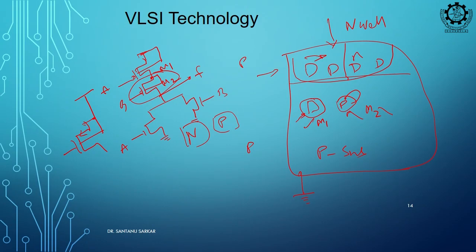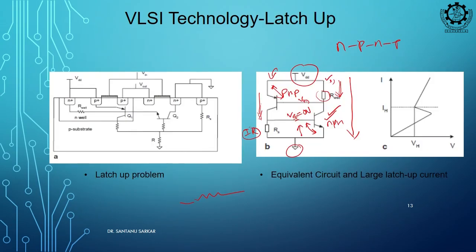See this circuit, these two R are actually generating this VB drop, right. If you can reduce this R, what will happen? IR drop will also reduce, and if IR drop is reducing, it will be difficult to generate the VB on, right. Base voltage is generated first. If base voltage is higher than the cutoff of that diode, then only it will get turned on, right.